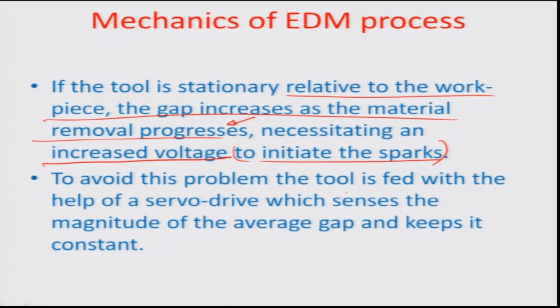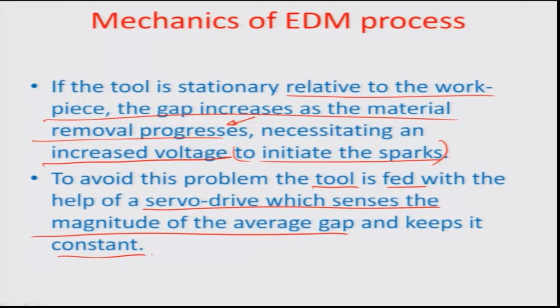So, the tool feed is the common strategy which is used for closing the gap as the gap gets enhanced because of this process of material removal. And so, typically a servo drive which senses the gap voltage and determines by comparison with the preset voltage keeps the gap more or less constant, so that the sparking process can be sustained.